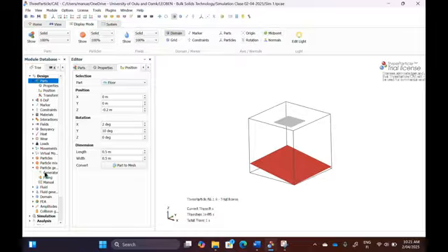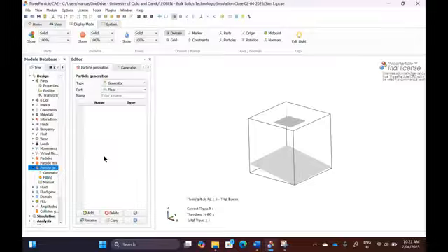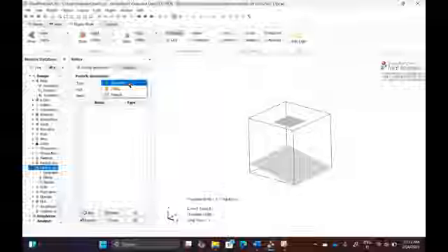And now we want to define how the particles are raining down from that plane. So the particle generation. Because this is what is meant with particles generated in the system. And then we see the type of generation. Yes, we have a generator, and the symbol says it. It's like a rain. You can also generate it in a different way. We'll come to that later. No worries. We can generate instantly, also a filling. But let's stick with the generator for now, because we want to have rain falling on our plane.